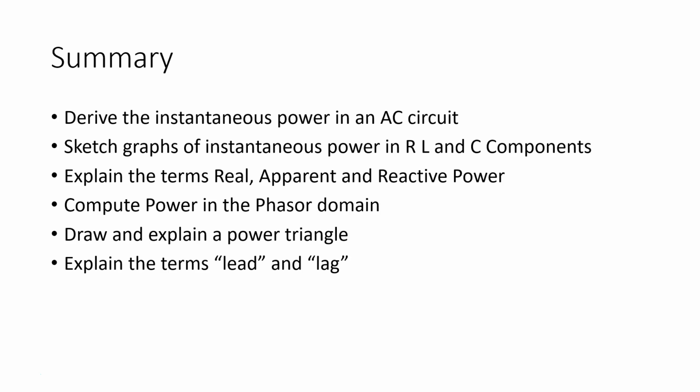You should be able to explain the terms real, apparent, and reactive power. You should be able to compute the power in the phasor domain. This is your S is equal to VI conjugate, and that is equal to P plus jQ. You should be able to draw and explain a power triangle and draw a power triangle from a circuit diagram and explain the terms lead and lag. And remember, with lead and lag, you're looking at the real power leads or lags the apparent power.